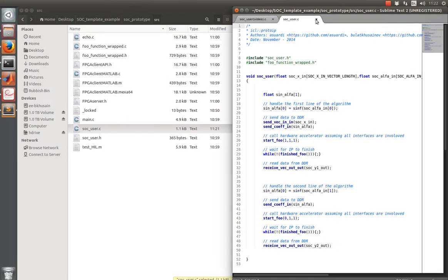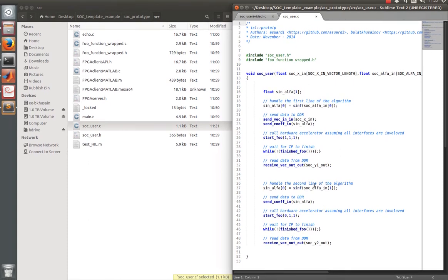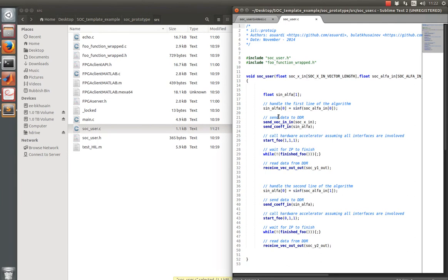The only reason why I did it via Xilinx SDK is because we have to link maths library via a graphical interface. But once I have linked this library, I can modify this code directly. And moreover, on Windows machine, as I have mentioned, there is even no need to manually link maths library.